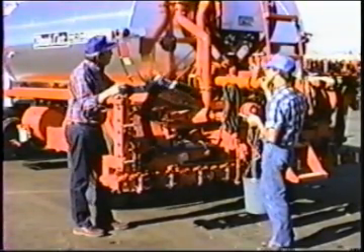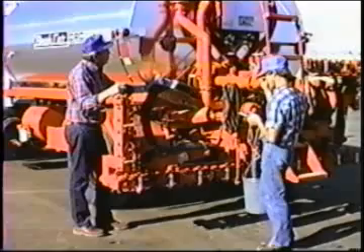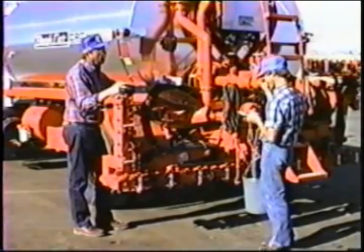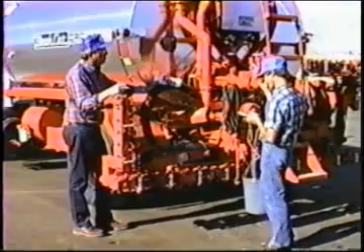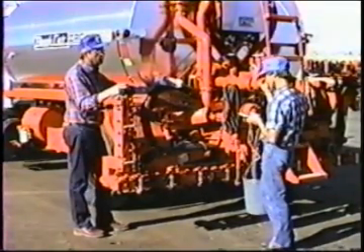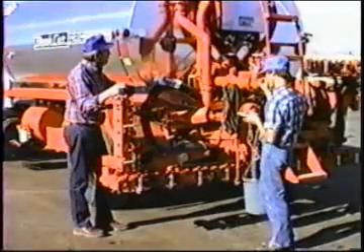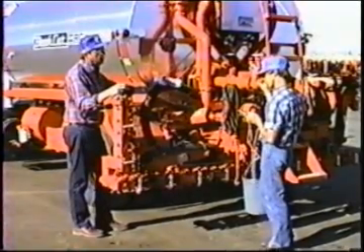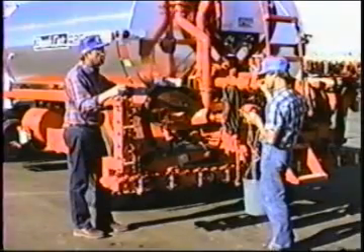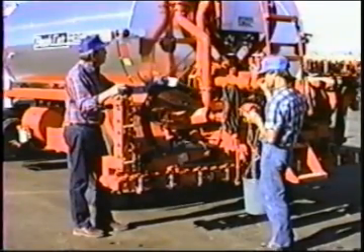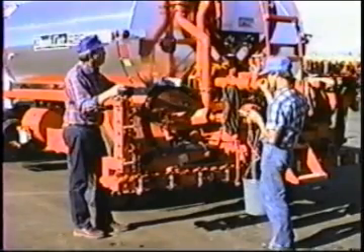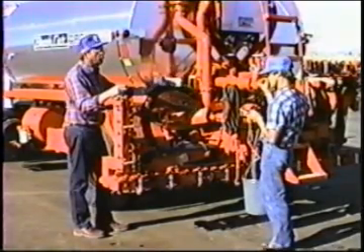If we had number 1 nozzles in it, you can see that's clear off the scale. We'd have tremendous pressure created if we were pushing 135 gallons per minute out through number 1 nozzles because of the little bitty hole. If we had number 2 nozzles in it, it's going to create a little less pressure. I see 20 pounds per square inch. Of course, number 3 we saw 8 pounds. Number 4 is a pretty big hole, so you can see it goes clear down to 4 pounds per square inch.